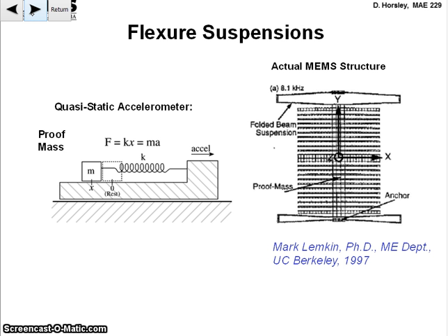Okay, so this is the picture that we look at, a simplified picture of an accelerometer, right? Here's a mass and a spring, M and K. This is the cartoon picture, and then this is the actual layout picture, for example, of an accelerometer. And what you can see here is it's been labeled as the x-axis, the y-axis, and the z-axis being out of the page. I'll try to be fairly consistent with that. So z usually we talk about as out of the plane of the wafer.